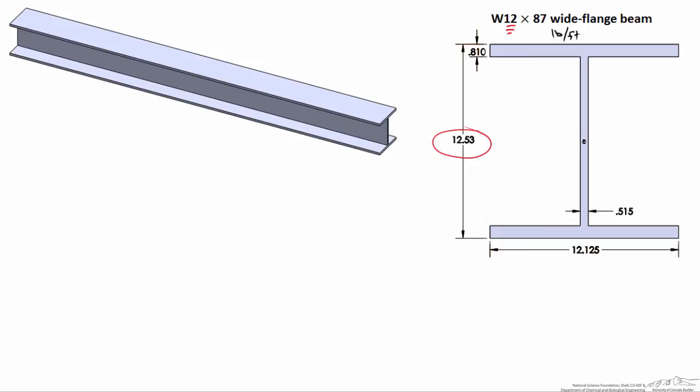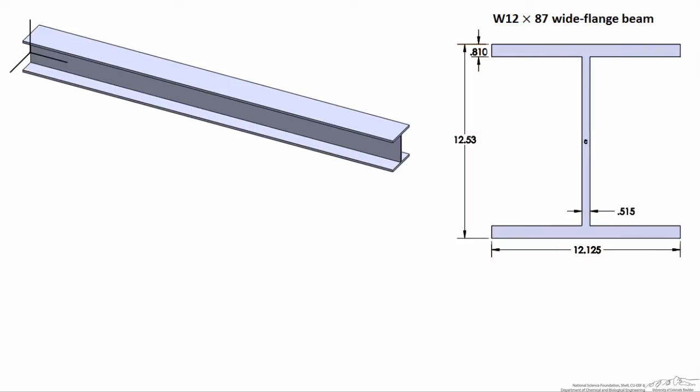So it means that each beam, the different sizes, could range anywhere from 14 pounds per foot up to 136 pounds per foot. And all of them nominally have this dimension of about 12 inches. And although this dimension stays at about 12 inches, what changes to change the weight is mainly the width of the flange. So a lighter beam would tend to have a narrower flange, and a heavier beam tends to have a wider, thicker flange.